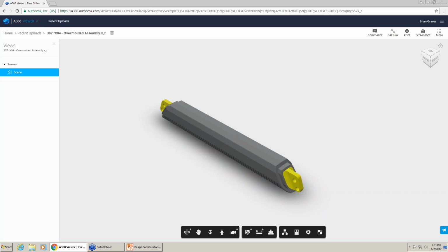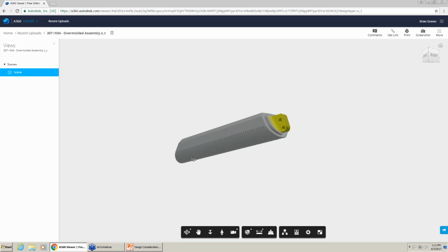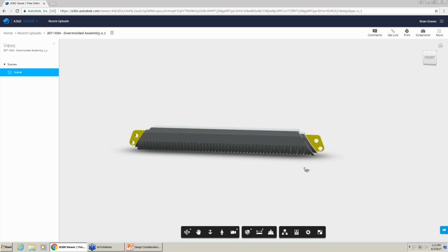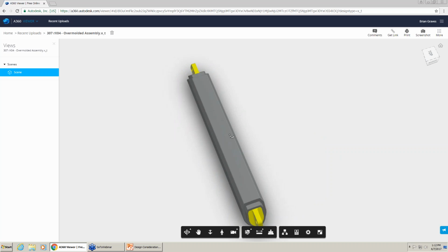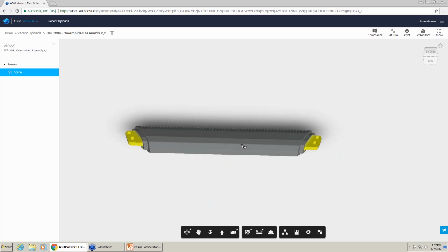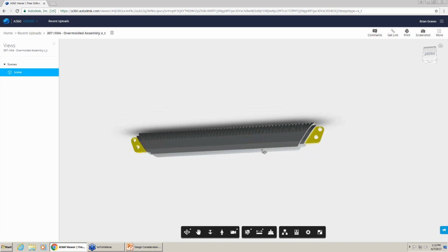And you saw a cross-section view of a part that was up on the slide, and this is the actual part that it comes from. This is an actual piece to a handle assembly, and this gray portion right here, this is the overmold. It's completely wrapped all the way around the substrate, and this is very tactile. This is a grip. This is all touch. This is so that when they hold this handle in place, it's gripping onto their hand, and this is going to be your substrate that flows all the way through this piece.